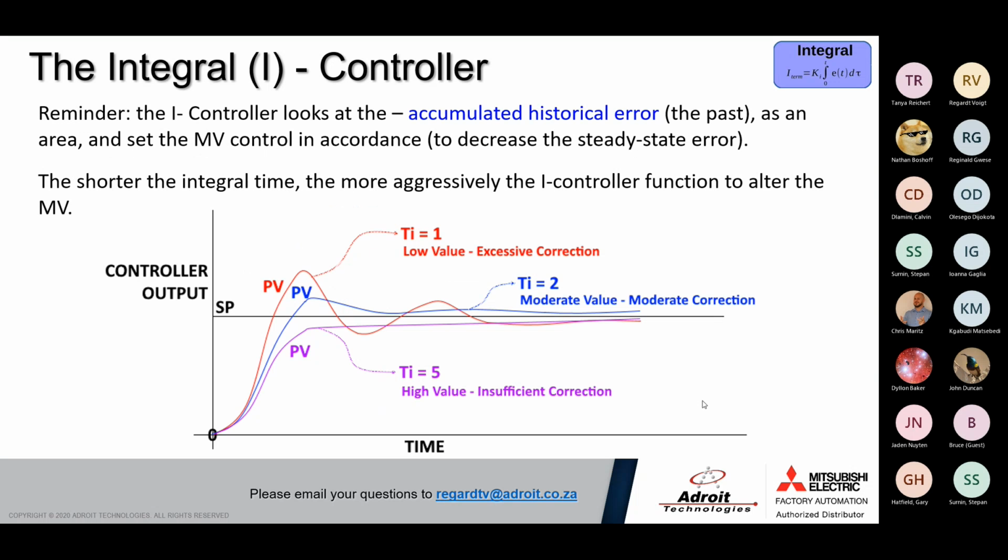Right. So here's another example with only the integral gains. If you exclude the proportional gains, then if the integral gain is too high, we will have undershoot. If it's too low, we'll have overshoot. So we need to get a balanced gain for your integral controller.